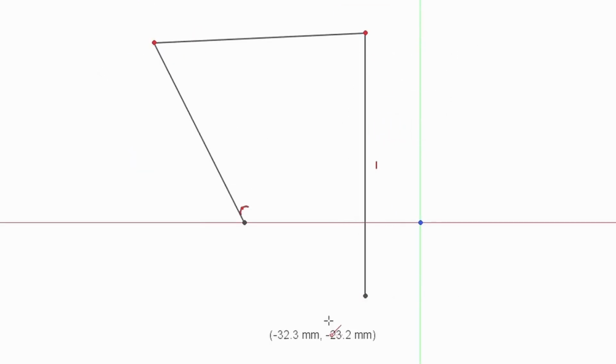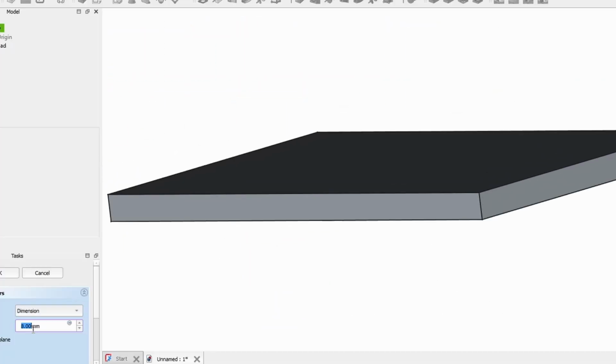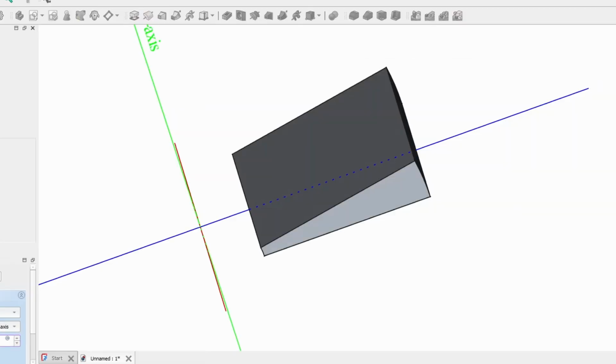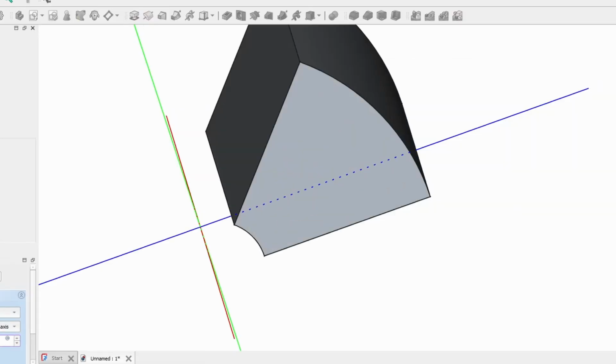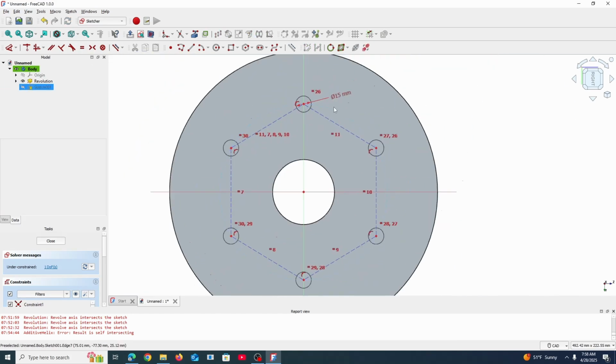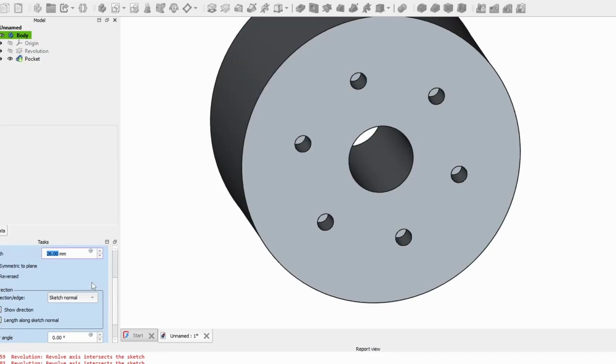So now onto the CADing process. Here's a basic breakdown of what we would do. We first make a 2D drawing and then make the size and features of that drawing to have the desired dimensions. Then we can take that 2D drawing and stretch it out into a 3D shape. There are many different ways of stretching which will be covered in this video. Then we repeatedly draw 2D shapes on existing 3D shapes to add on material or take away material until we get what we want.